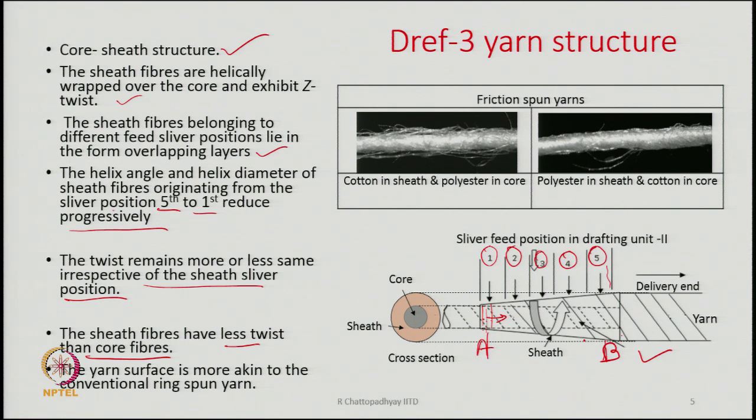It is not that it is always in contact; sometimes it loses contact because of the lot of centrifugal force acting between them. A lot of air turbulence also gets created there. So, all of this means there is a possibility of the yarn tail losing contact on the drum, and therefore there is a lot of slippage.